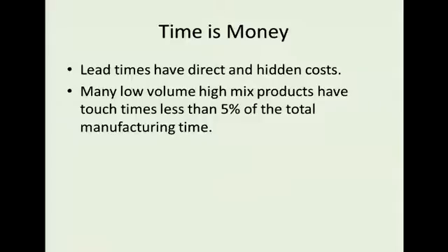Time is money. Lead times have direct and hidden cost. For high volume, low mix manufacturers, the touch time is usually much less than 5% of the total lead time. You're waiting for parts, you're waiting for machines, etc.